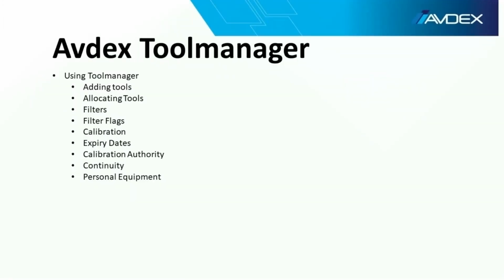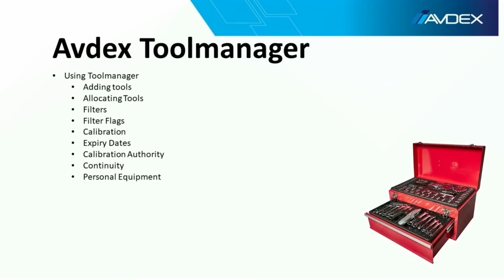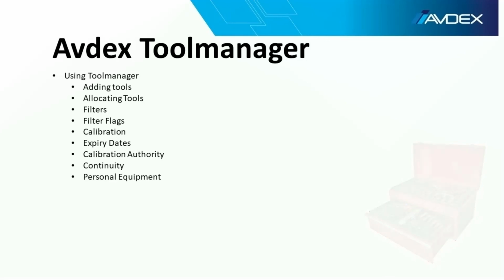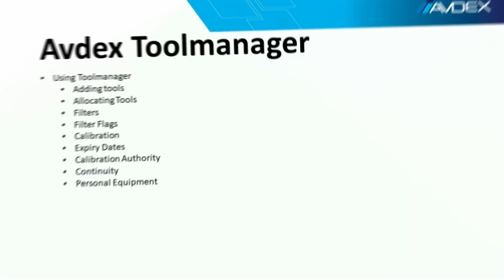Personal equipment. A maintenance organization should detail, in its manual of procedures, or equivalent document, its policy relating to the use of personal tools within the organization. If the use of personal tools is permitted, then the policy should require those personal items of equipment to be appropriately identified as personal equipment, whether they are calibrated or not. The organization may elect to control the calibration of employees' personal equipment. This includes handheld tools such as crimping tools, multimeters, torque wrenches, etc.